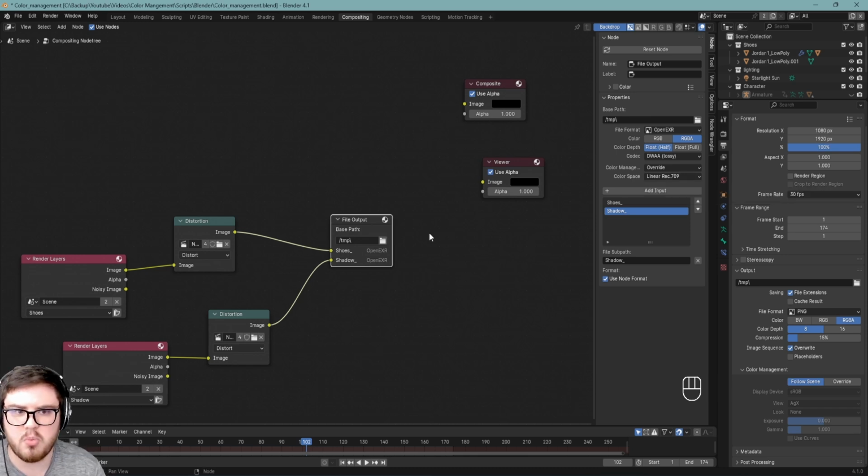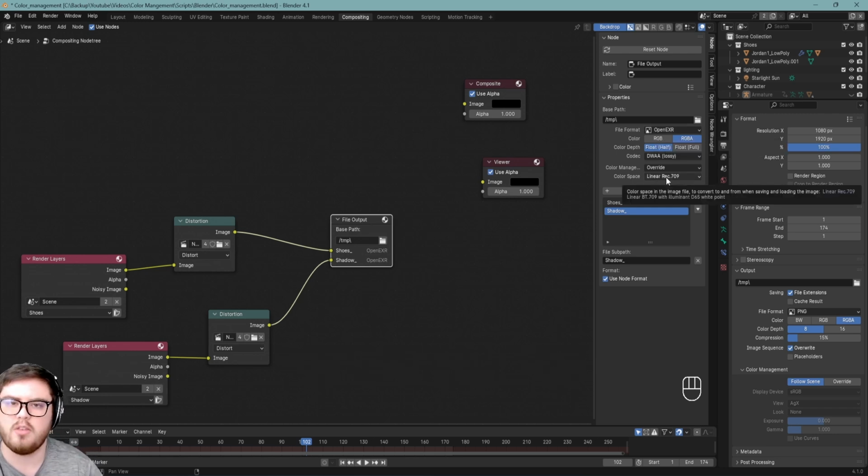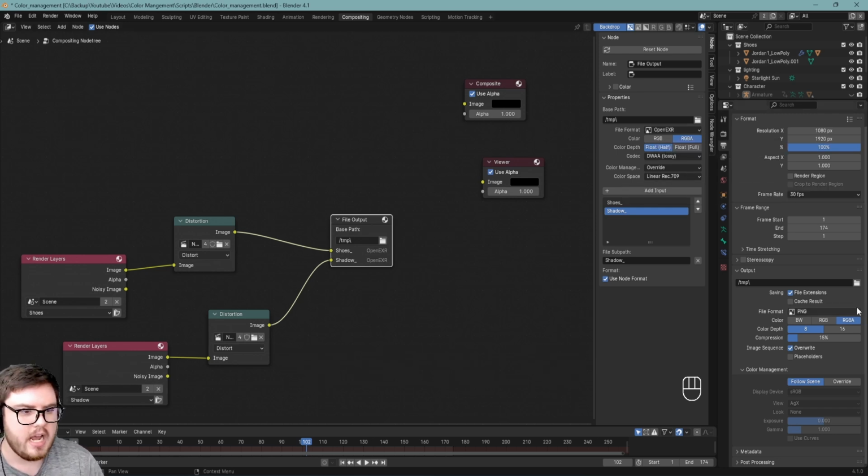But that's super, super important, guys, because in the compositing process, we have to have linear Rec 709 for the CGI and footage to match as perfectly as it did inside of Blender. And so just keep that in mind. EXR sequences will typically do Rec 709. That's why we converted it inside of Davinci. And then PNG, TIFF, JPEG, MOV files will do an sRGB color space and apply the AGX. So hopefully that all makes sense.